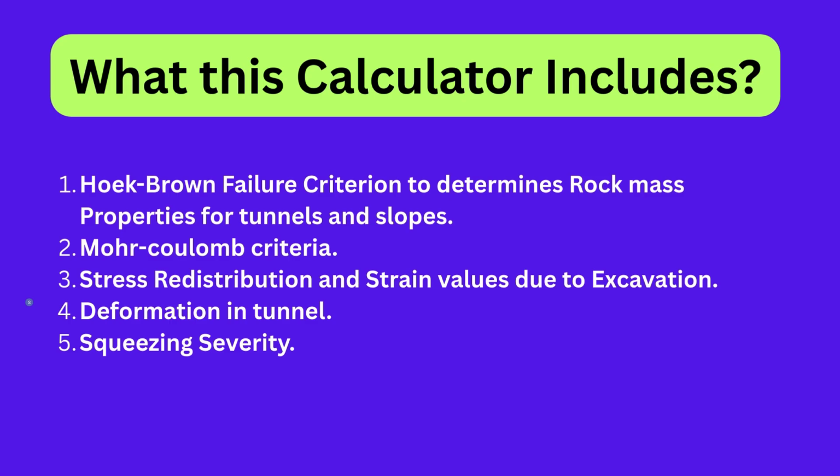It will determine rock mass properties, C and phi values of rock mass, stresses and deformation in the tunnel crown and walls. The important factor we will determine will be the severity of squeezing and deformation in the tunnels due to in situ stresses, depth of tunnel, and the quality of rock. All these parameters we will find through this calculator.